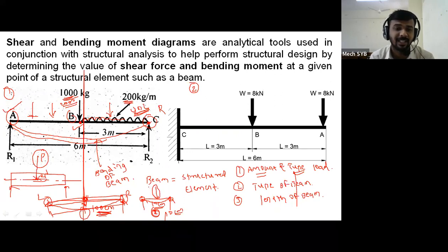जेवढी त्या बीमची लेंथ जास्त असेल तेवढी त्याची बेंडिंग होण्याचे चान्सेस जास्त असतात. आणि जेवढी बीमची लेंथ तुमची कमी आहे तेवढा तो मॅक्सिमम लोड सस्टेन करतो. दॅट्स व्हाय आपण बघितलं असेल इन सम ऑफ द ऍप्लिकेशन, इफ लेंथ ऑफ एनी स्ट्रक्चर इज इन्क्रीजेस, एखाद्या स्ट्रक्चरची लेंथ जर वाढत जात असेल तर एका ठराविक लेंथनंतर लगेच त्या ठिकाणी आपण सपोर्ट टाकतो. अजून ठराविक लेंथ झाली की लगेच आपण दुसरा सपोर्ट टाकतो. अजून थोडी लेंथ वाढली की आपण तिसरा सपोर्ट टाकतो. सो व्हाय इट इज लाईक दॅट? बिकॉज दॅट पर्टिक्युलर स्ट्रक्चर इज डिझाईन्ड फॉर द पर्टिक्युलर ऍप्लिकेशन. त्यामुळे त्याची एक ठराविक लेंथ कॅरी आउट केली की लगेच आपल्याला दुसरा सपोर्ट द्यावा लागतो. इफ वी आर नॉट गिव्हिंग द सपोर्ट आणि त्या बीमवरचा लोड इन्क्रीज झाला तर देयर इज अ पॉसिबिलिटी ऑफ फेल्युअर.